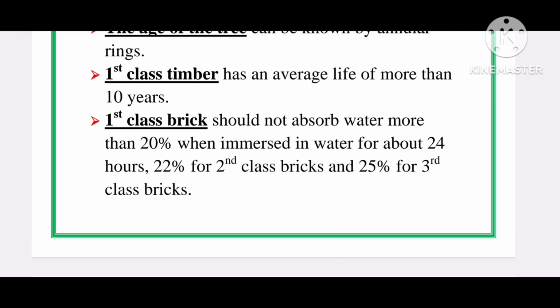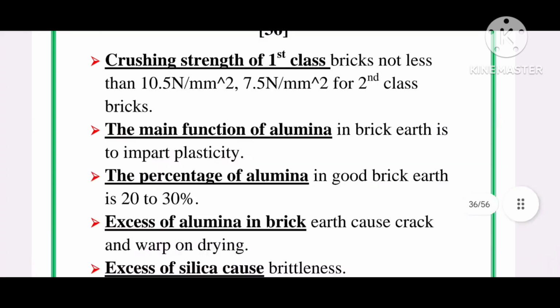First class brick should not absorb water more than 20% when immersed in water for 24 hours, and 22% for second class bricks and 25% for third class bricks. For first class brick, water absorption should not be more than 20% when immersed in water for 24 hours; for second class brick not more than 22%, and for third class brick not more than 25%.